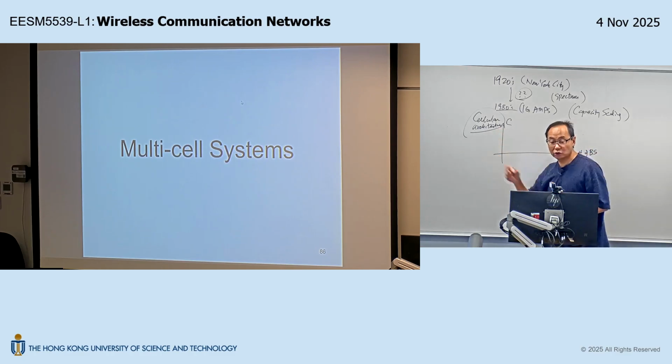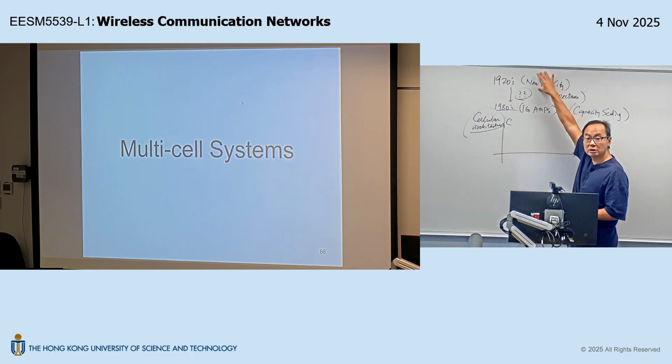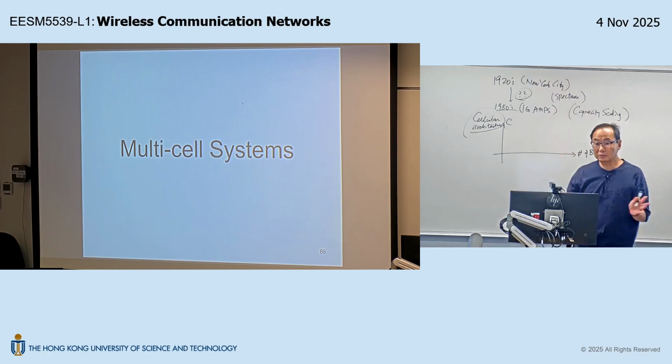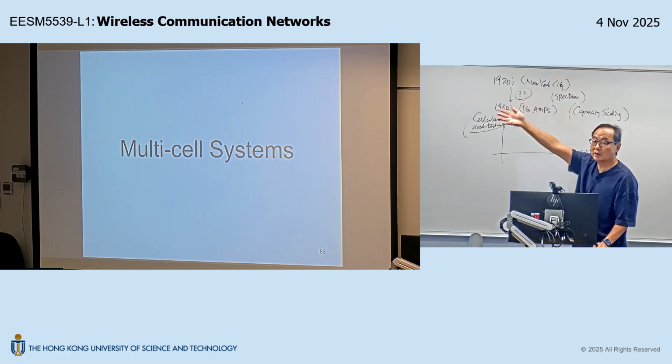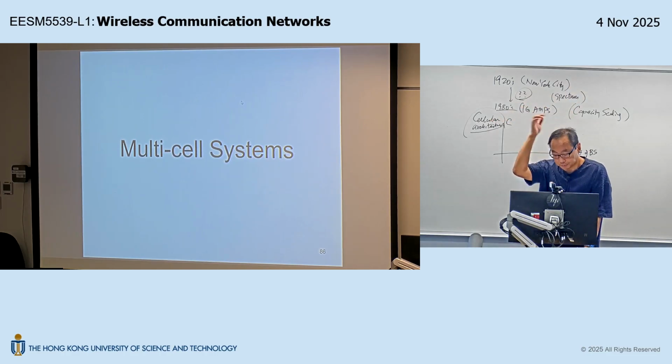By the way, cellular architecture means we try to split the coverage area. Now, before cellular architecture, in the 1920s system, the architecture was very simple. You want to minimize the infrastructure cost to provide good coverage. So at the end, the solution was you install a few radio towers on some very tall mountains, blasting very large power, just like today's TV tower. Just to give an example, in Hong Kong, the TV and radio broadcasting tower is only less than 10 transmitters to provide the entire coverage for Hong Kong, okay, for TV and radio.